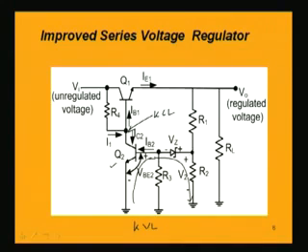The direction of the base current in the first transistor will be towards the transistor, because it is an NPN transistor, so P must be positively connected, so the current direction will be like this. That means at this point I1 equals the incoming current, equal to the sum of the outgoing currents IC2 plus IB1.